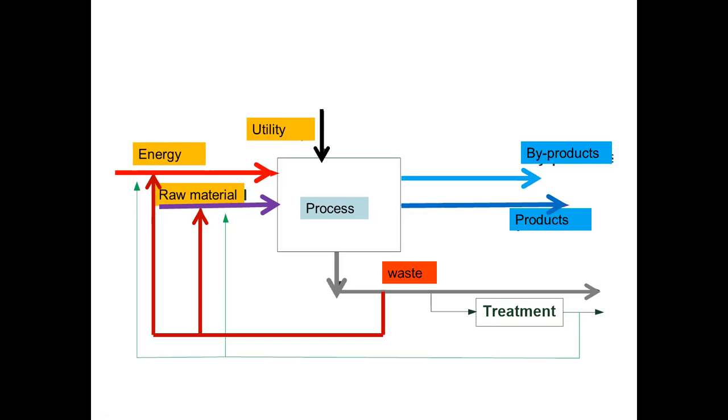So in the parboiling rice industry, paddy rice husk is taken as a fuel to run the boiler, because in the parboiling rice industry, the paddy has to be boiled by using hot water or steam. It depends on the type of the process. To make the hot water or the steam, they have to run a boiler. The boiler is run by the fuel, which is the rice husk.